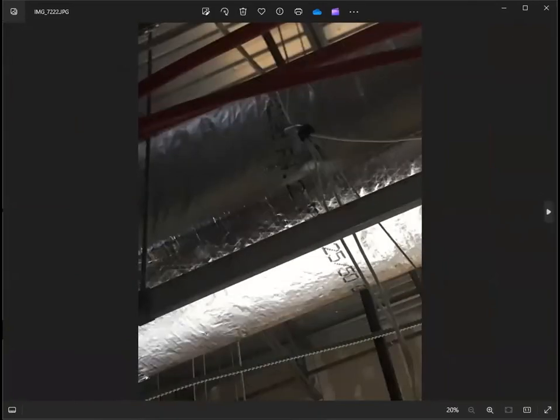There is an exemption if the engineer will see to that exemption and say this is okay for the job, because I think this is conditioned air and there is a 10 degree Fahrenheit, I believe, difference for the ductwork to be insulated or not insulated.